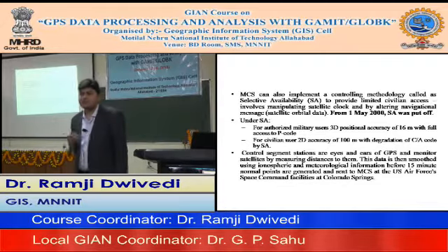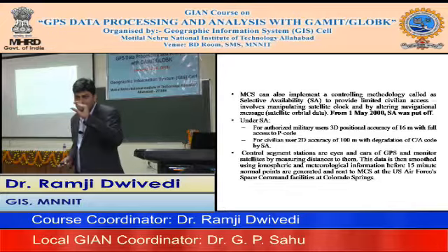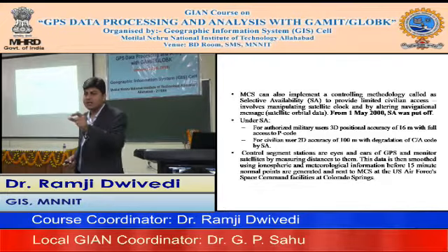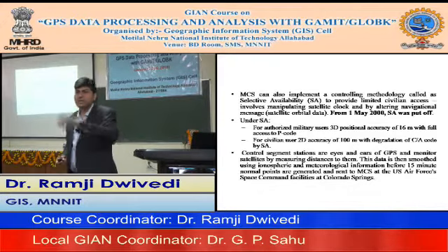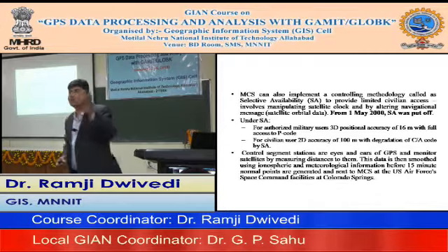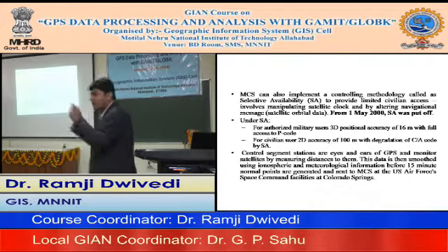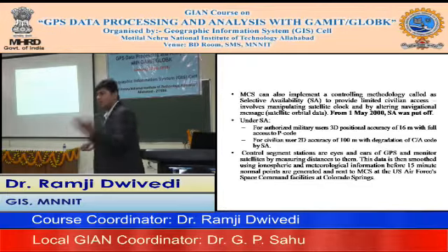What was being said in the first half is that if your clock information is poor, that means if you have an error in your clock of microseconds, you can calculate that the position changes, since the satellite is moving at about 3 kilometers per second. So you could see that with a microsecond error in your clock, you are nowhere on the earth; you are somewhere beneath the earth, isn't it, if you are calculating the range.